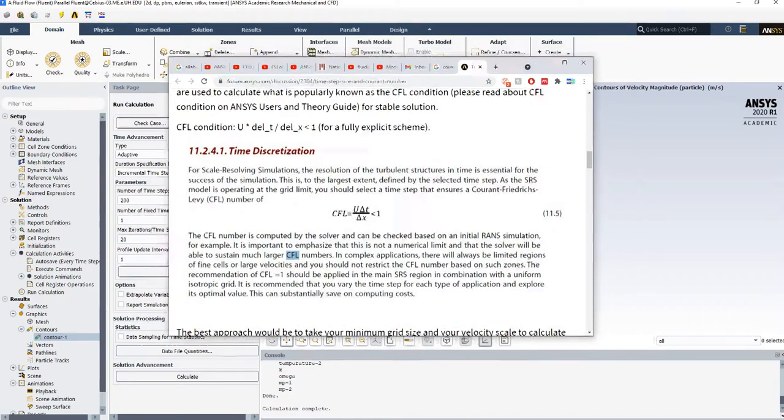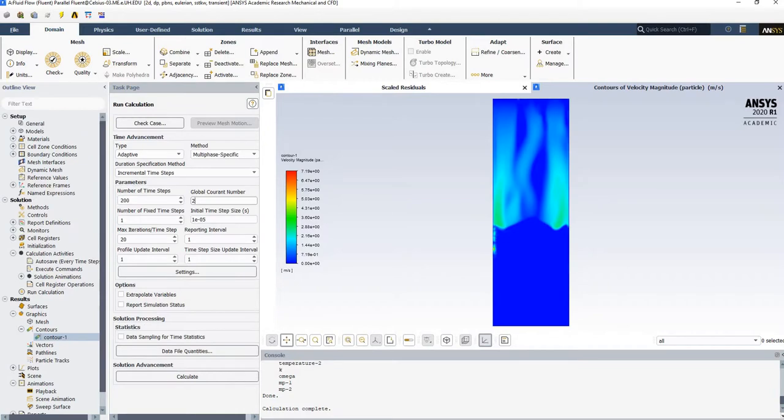So this is one method to stabilize the simulation, but the problem you might see is, if your other boundary condition is not suitable, like it's extreme, then your time step size will go very small, and it would take an endless time to complete the simulation. So again, I would not recommend that, but if it's not working and you just want to see if it works or stabilize the simulation at the very beginning, you can use this method as well.